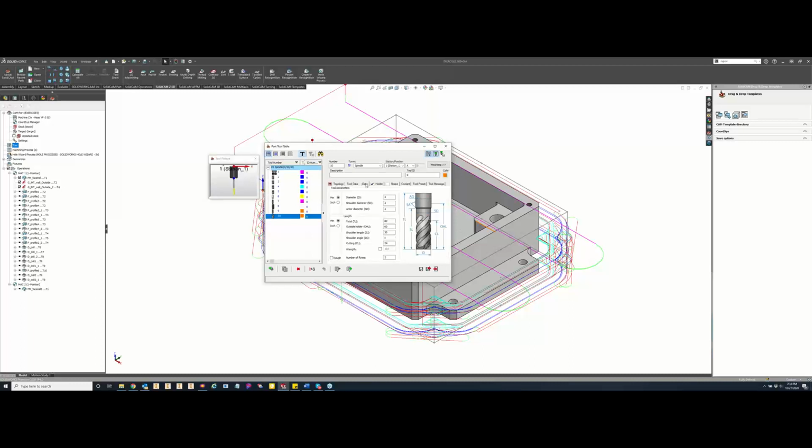So if we go to our iData tab, I have the option to select from carbide, cobalt, high-speed steel, and premium carbide. Like I said, the premium carbide is going to be your coated end mills. Here we have the standard helix angles, but if you're running into like a 42-degree helix, just type that number in there. Even though it's not a drop-down, you can type that number in and it will bring the data in for you.